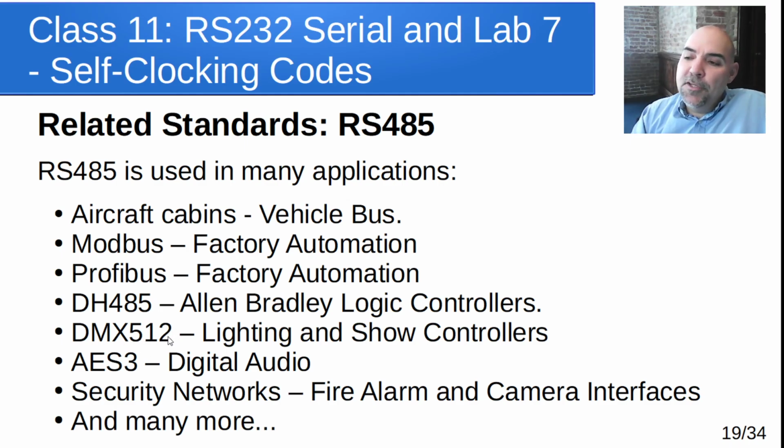There's also digital audio. If you have a digital audio connector on the back of your high-end stereo equipment or synthesizer or sampler or whatever, and it's an AES3, that's actually RS485 that's communicating digital audio information between the devices. Also, a lot of security networks like fire alarms, smoke detectors, security camera interfaces for motion detecting and stuff like that.